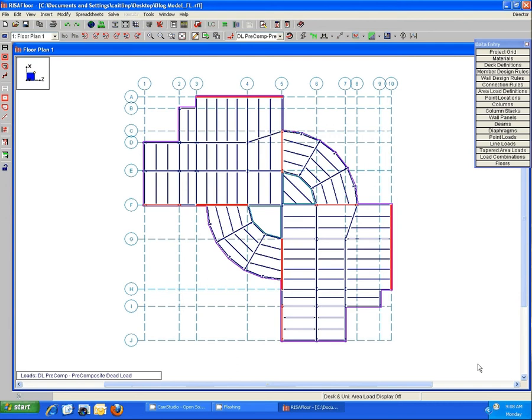But I thought it was a good model because it shows a good combination of lateral elements, those are shown in red, and gravity elements, which are shown in the navy blue here. Now the same basic rules apply in order to get RISAFloor elements into RISAFoundation. You must have the y-axis as your vertical and you must assign load categories. However, because of the nature of RISAFloor, most of this is automated for you, so you don't have to do much to set this up. It's going to be done for you just based on the 2D view of the program.